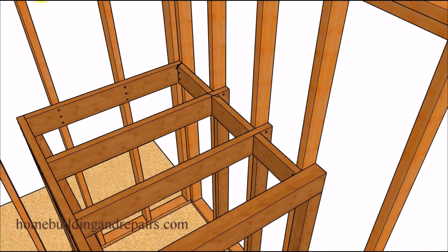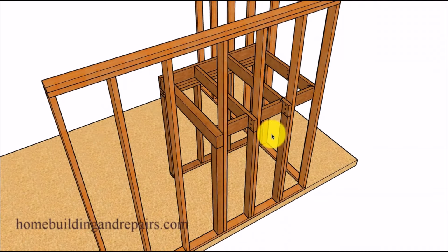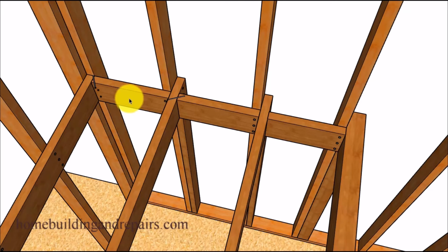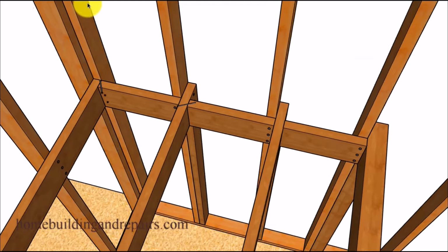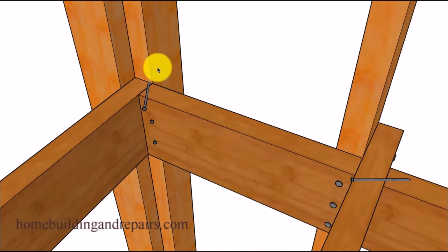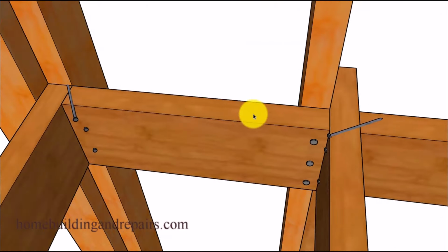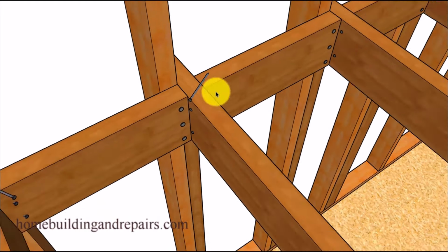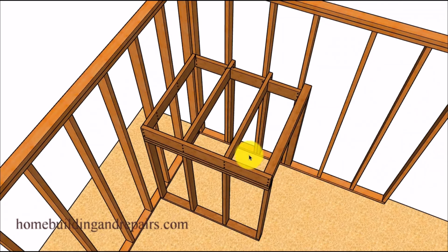So this method here is going to require a little more materials, and we will block between the joists instead of using a ledger. And this method right here could save you a few dollars depending upon the price of lumber and the price of building hardware during that period of time. And the joist will nail into the wall framing studs along with the blocks. And of course you can angle the nails again at either end. Here we're angling them into the block. So again, another idea that will provide you with a stronger landing.